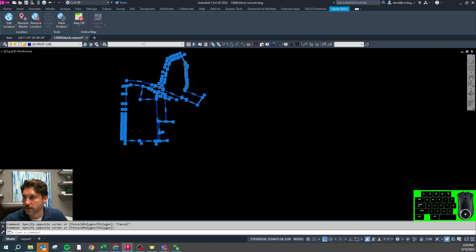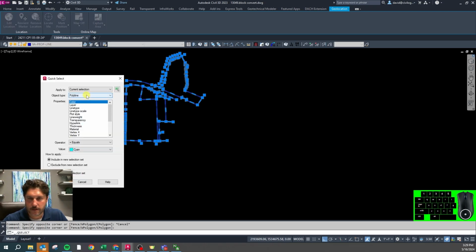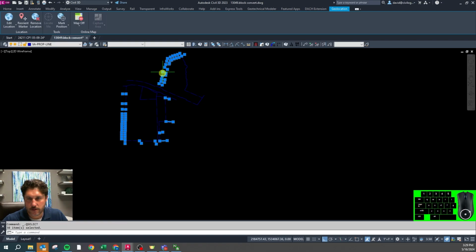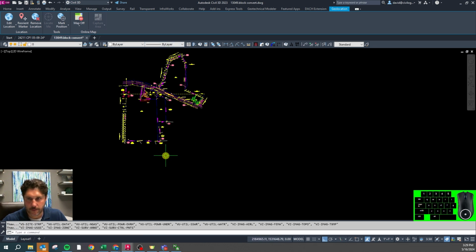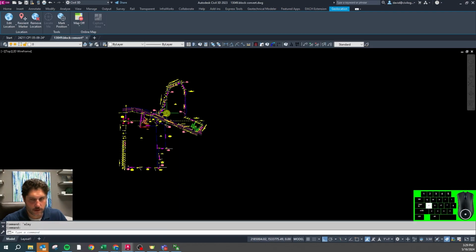These I'm going to select, because we like our main property to be blue. I'm going to use the filter command, and I'm going to pick the color is not equal by layer. And so I'm going to get these other ones, and then I'm going to change that to white. I'm going to run the command ZX again to get back to where we were.